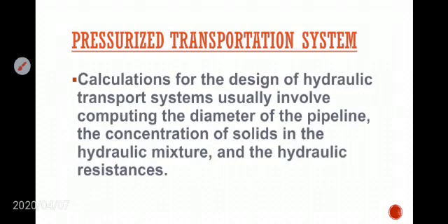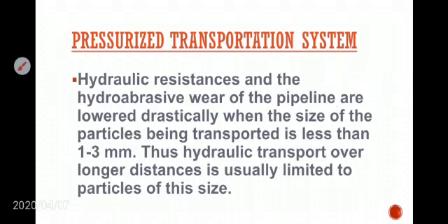And in order to successfully carry out this pressurized transportation system in hydraulic mining, we need to initially do some calculations appropriately for the exact design of hydraulic transportation systems. In those calculations, we need to consider some parameters like diameter of the pipeline, concentration of the solids in the hydraulic mixture, and the hydraulic resistances.